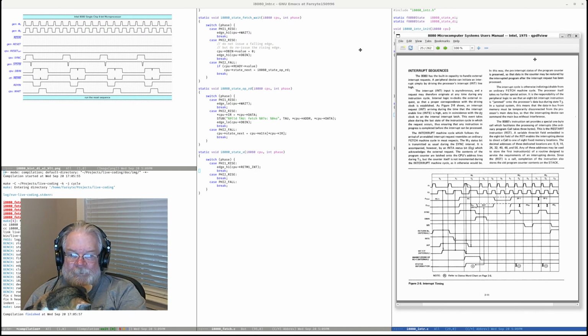So for the interrupt timing, INT enable is either high or low. It will be dropped low during the process of taking an interrupt, which we're not going to start on quite yet. But this means INT E needs to be put high when we're enabling it and low when we're disabling it, and that needs to happen on the rising edge of phi 2.